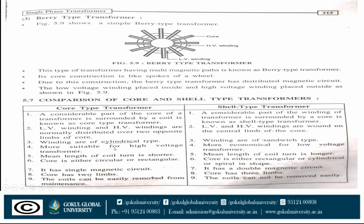Core type is more suitable for high voltage transformer, and shell type is more suitable for low voltage transformer. Mean length of coil turn is shorter in core type, and mean length of coil turn is longer in shell type. In core type, core is either circular or rectangular. In shell type transformer, core is either rectangular or cylindrical or spiral in shape.